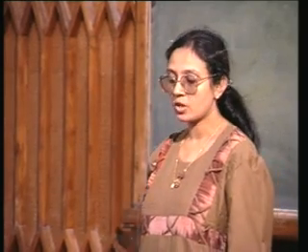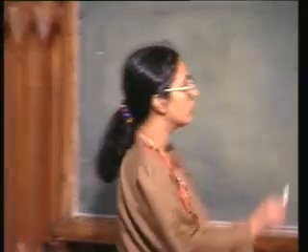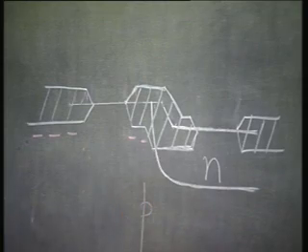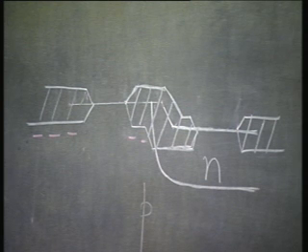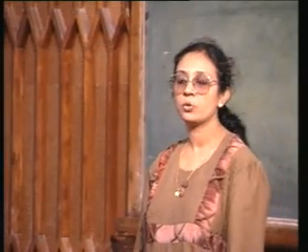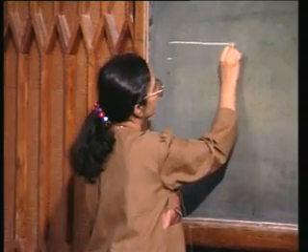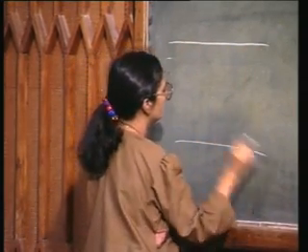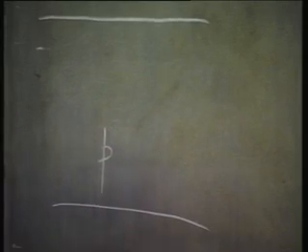Now, in the twin tub technology, we will actually form two wells. In this case, we have formed only one well, that is the Nwell. In the twin tub technology, we are going to form two wells. So, you start with a very low doped P-type substrate.